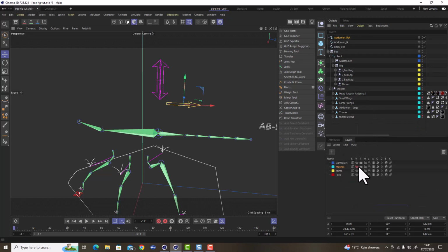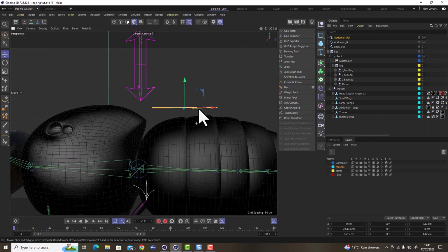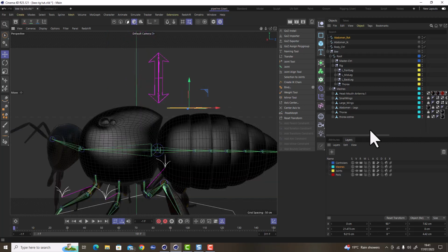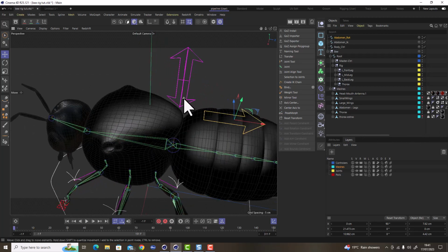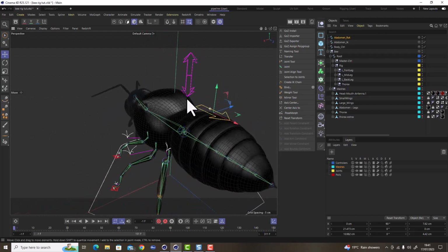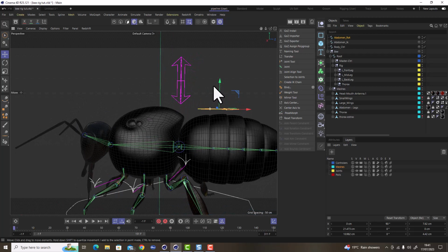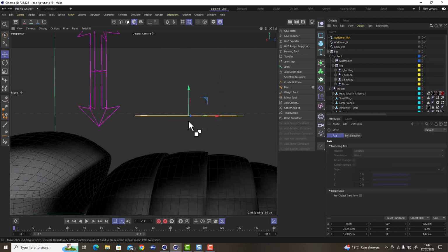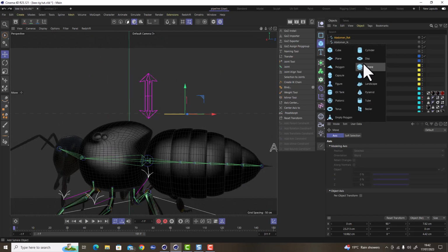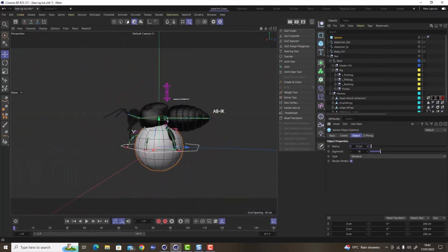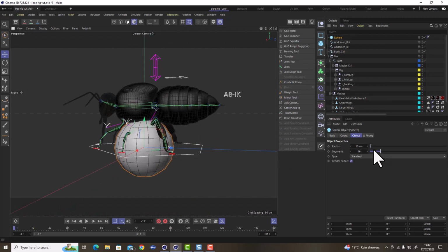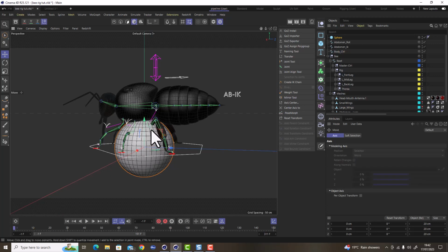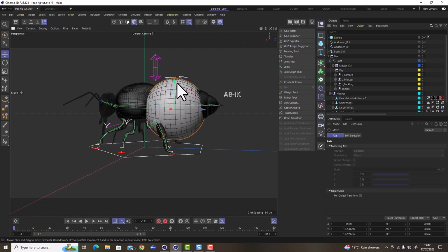So that's turn on our layers meshes, and I want to project that against this, and I want to move it and keep it clear of this so we don't get too close to it. I think that would be fine. So what I'm going to do is I'm just going to create a sphere, and we're going to make it nice and smooth. I'm going to rotate it 90 degrees, and I'm just going to use it as a proxy object to create this shape.